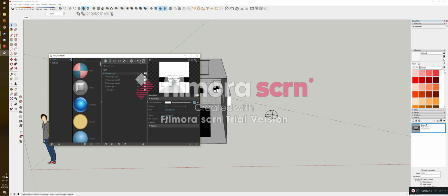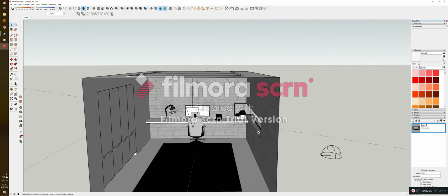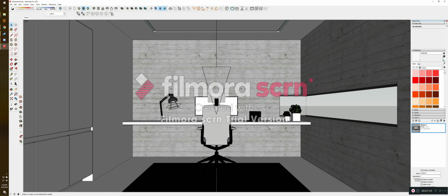And we're going to go back and also set this to a sphere for the shape, because we do not want the SketchUp horizon line interfering with our window should that horizon line be at the window. So we can see here that we have a mountainous background with no fake horizon line. That's perfect. So let's go back into our scene, see what it looks like.